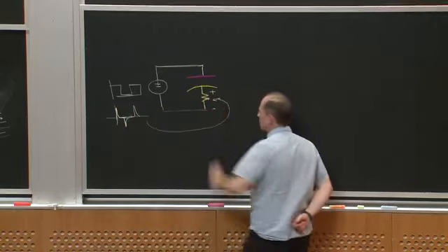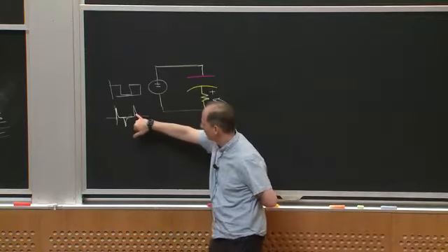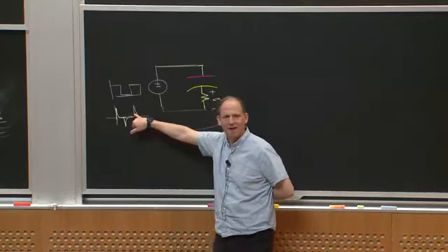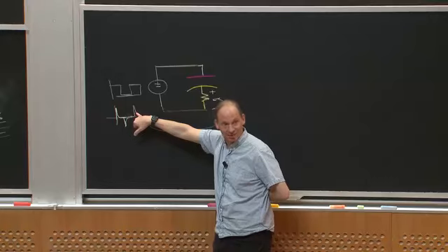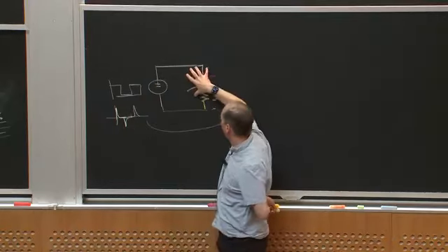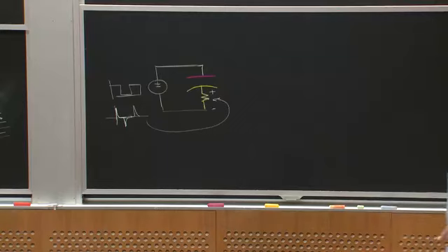So this is the voltage I'm going to see here. Does that make sense to everybody? Maybe the energy in these spikes isn't very big, but if that's the input to a comparator, maybe I'm very unhappy, right? Because if that comparator is determining when the switch turns on and off, and I get a spike on that signal because of this capacitive injection, I could be really unhappy. Any questions about that?